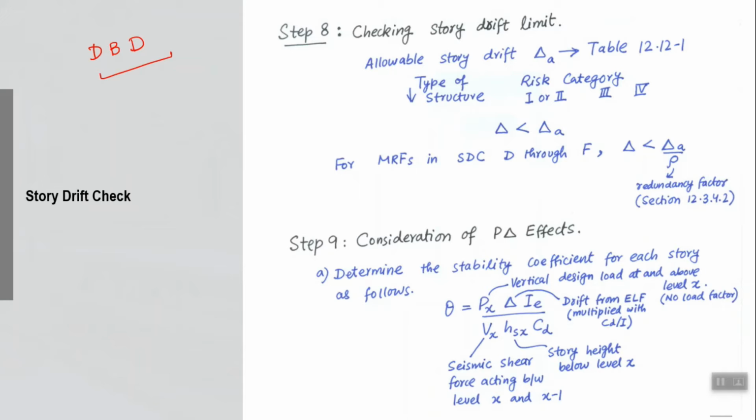But currently the conventional code based design is called force based design, because the main design variable is the design force against which the capacity in the form of force is provided. So you calculate an Mu, for example, and provide Mn against that, right? The maximum design action in the form of force is calculated and the capacity in the form of force is provided, Mn, right? Similarly, Vu will be provided with a capacity Vn, Tu with Tn, axial load Pu with Pn, right?